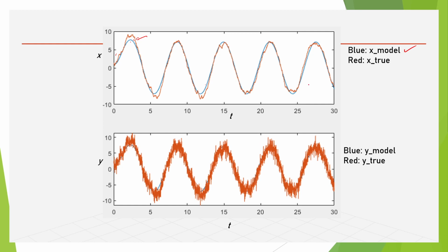And here is just an uncertainty on the dynamic model itself. But if we want to measure something, our sensor also introduces some corrupted data, some noise. So the orange here is the true state, and then we want to measure it, and we get additional noise here. The orange one is very noisy.